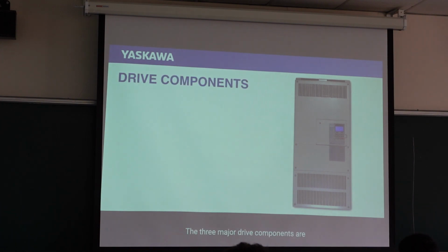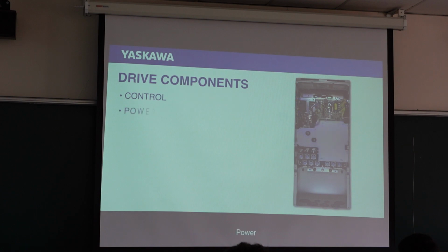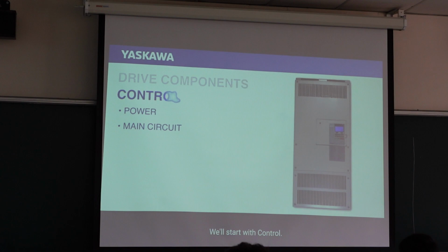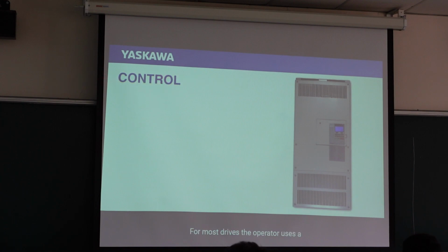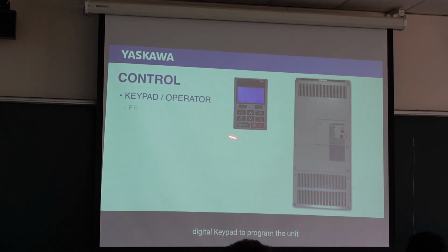There are three major drive components: power, control, and the main power circuit. We'll start with control. For most drives, the operator uses a digital keypad to program the unit for the given application. And in some cases, to control the frequency, operate the drive locally via the keypad.